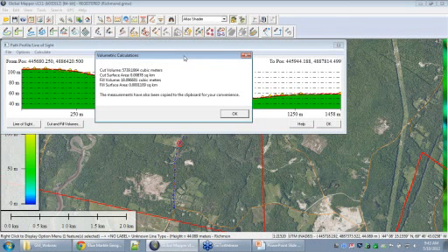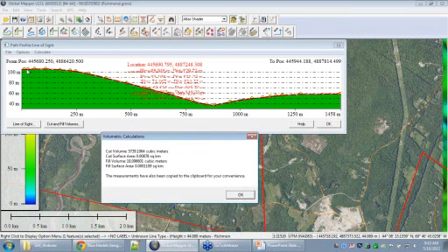So we're going to have to figure out where we can haul 5,700 cubic meters of dirt off to, and we're also going to have to come up with that amount of fill to put back in over the course of that line. It gives us things like the fill surface area, the cut surface area, how much we're going to be digging out and filling back in some of those various places as they interact with that terrain model.